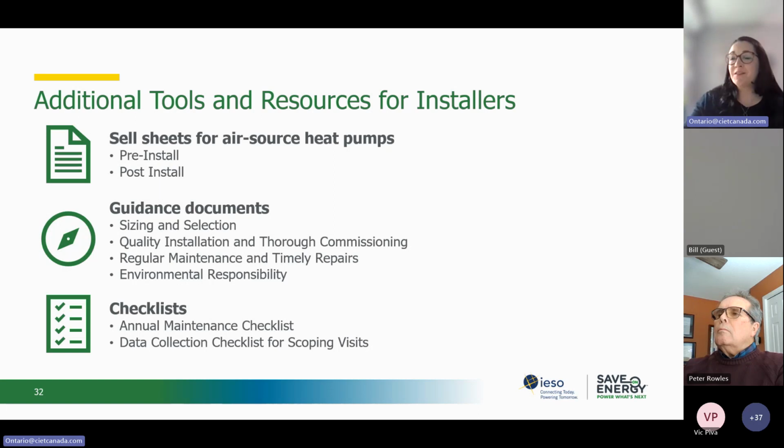Regardless of the heat loss, the heat pump size seems to be limited by the airflow capability of the duct system. That's definitely something that needs to be considered during the investigation, sizing, and selection stages.